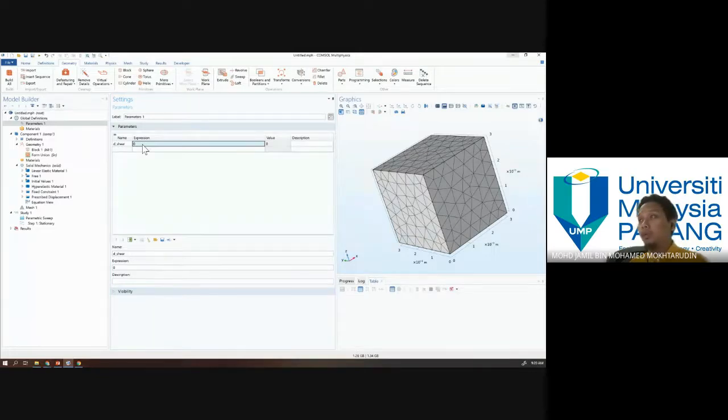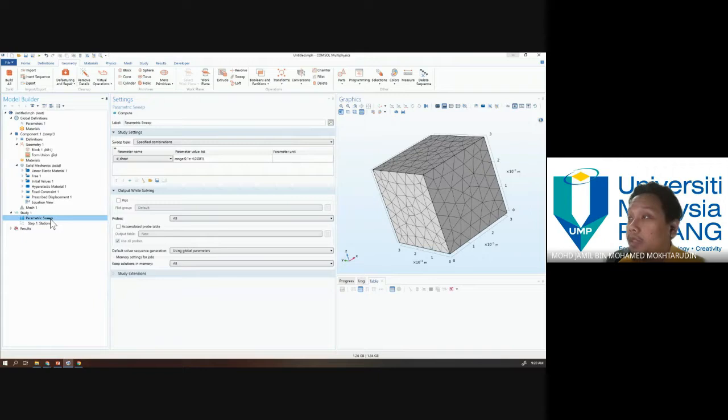So you would need to open 10 consoles, 10 times, and it might consume a lot of RAM and computer power, or it will slow down your PC. So by using parametric sweep, we choose the parameter that we want, and then we choose the parameter values that we want the simulation to run.